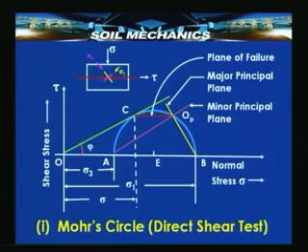First, the direct shear test. What is important here is to understand how the stresses vary in the different planes during a direct shear test, which is the failure plane, what is the value of the stress during failure on the plane of failure, and how does the failure plane lie in relation to the applied stresses or the major and minor principal stresses.